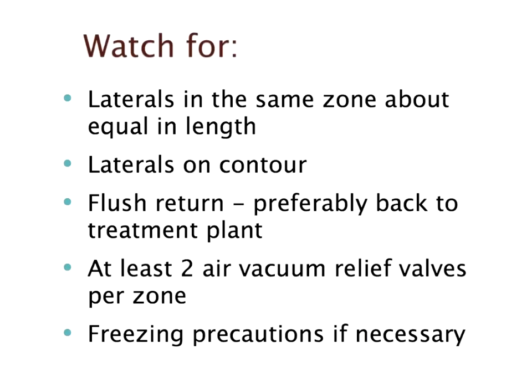I mean, 10% is just fine. That's not going to affect it to any great consequence, but sometimes you get triangular fields where people don't think of S-ing the lateral to get 2 or 3 vents to even up the vents of the laterals. You want to hold your laterals on contour.